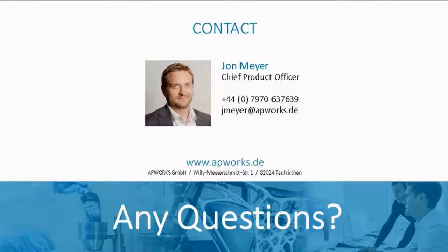And so that's the process that has been followed. There are qualified serial production applications of powder bed metal additive manufacturing in service today on civil aircraft. In fact, they've been applied on military products for quite a long time. So I'd say the status is pretty mature, but again, for a very particular scope today. So as always, if you want to expand that scope of materials or that scope of application, so today we're talking about non-safety critical parts, class 3 parts, then that's one hurdle to get over, which has been achieved.